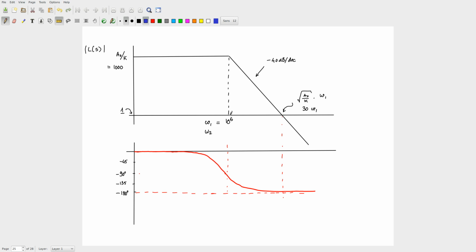No. Right, left. Okay, go back and see. You have your omega 1 here, right? Your omega 2, your P2 we discussed was 4 times your new unity loop gain frequency. So if this is here, it should cut to the left, right? Okay. So just think a little bit. So I am just drawing it like a little stub there, and then I drop like that, something like this, right, up to here, and then it should go at minus 40.